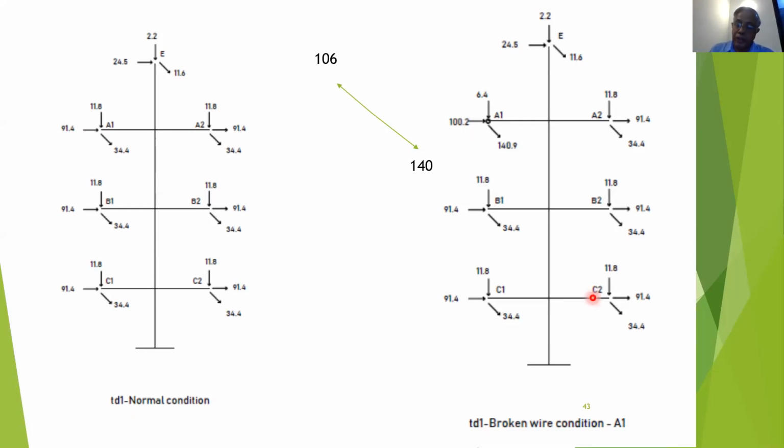Like that, we are checking for broken wire conditions, and this is the load tree which we are using to design the towers and foundations, because those are the maximum loads that they are going to face. So for that loads, the design is performed.